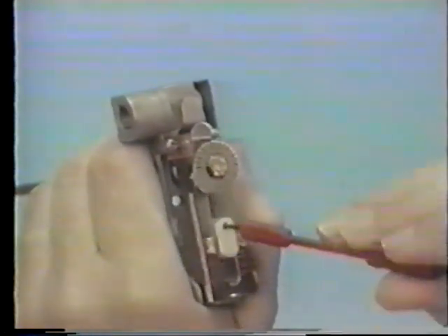To check calibration, measure the ambient temperature at the sensing element and adjust the set point dial to match that temperature. The branch should be 9 PSIG. If not, turn the zero adjustment with a 1/16-inch Allen wrench until the branch pressure returns to 9 PSIG. Now, return the set point adjustment to the desired set point.